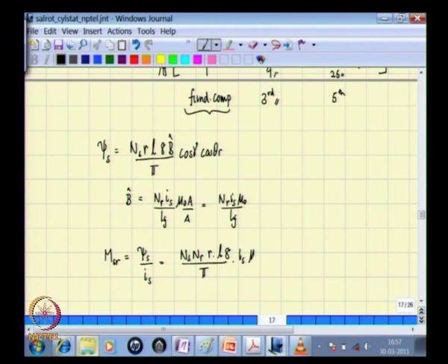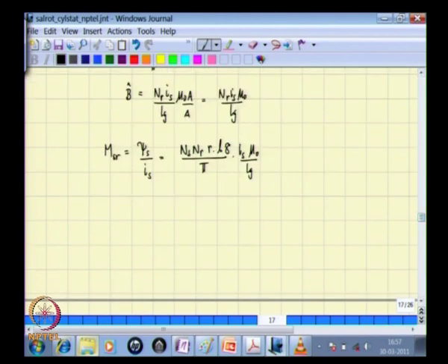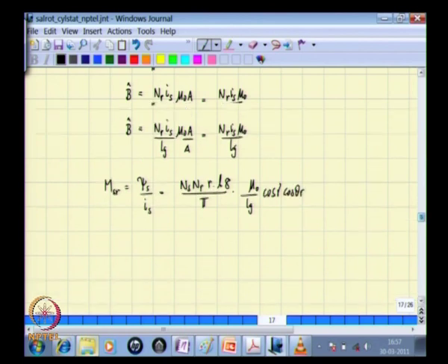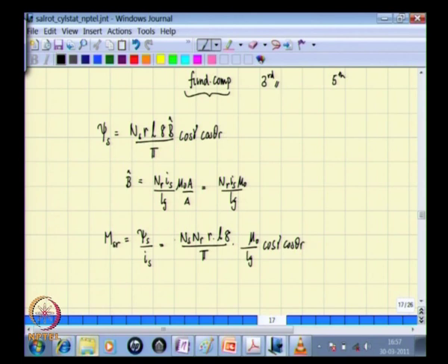So, that is is into mu naught by Lg, and psi s by is would mean that is is no longer there. So, this is then the mutual inductance multiplied by cos gamma cos theta r, and therefore, this term one can call as the peak value of mutual inductance MSR hat multiplied by cos theta r.